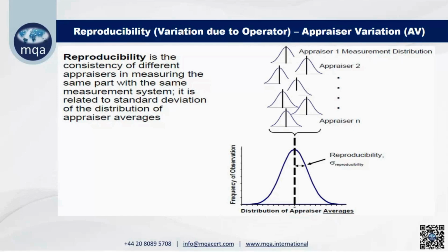So we have to take care of both. What do we have to take care of? Repeatability and reproducibility. Because while measuring data, we cannot ensure that the person taking the data today will be available tomorrow also. Maybe he may be doing some other process. Suppose I have to take 100 readings. Today I told one technical person to take 50 readings.